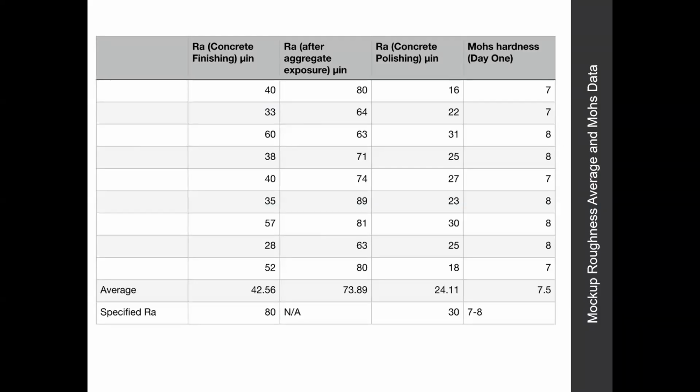And the sustainability, again, if your concrete is denser, if it's harder, it's going to last a much longer time than something that is softer. And when you're in a situation, and Mark, I know you do a lot of industrial facilities, where you're being told, hey, let's have a change order, we'd like to put on metallic dry shake hardener. Well, if your facility is already measuring at 8 plus, quantifiably, there is no benefit to adding on a metallic dry shake hardener, which is also going to give you 8 plus. You're already there. So there's a cost element, there's a schedule element, by just measuring what your progress is doing. Let's go to the next slide here.